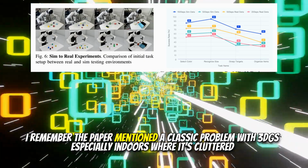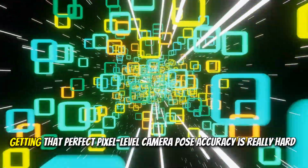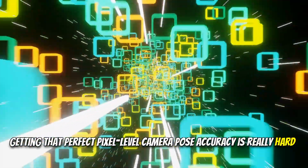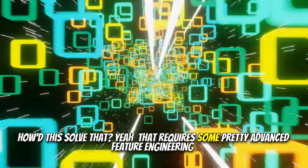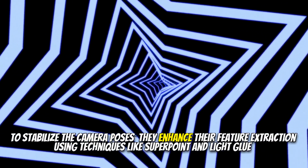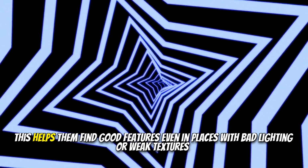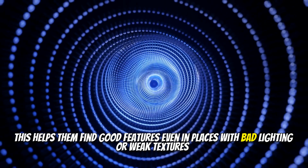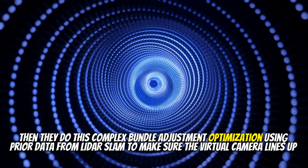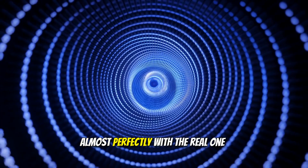I remember the paper mentioned a classic problem with 3D-GS, especially indoors where it's cluttered. Getting that perfect pixel-level camera pose accuracy is really hard. How'd this solve that? Yeah, that requires some pretty advanced feature engineering. To stabilize the camera poses, they enhance their feature extraction using techniques like SuperPoint and LightGlue. This helps them find good features even in places with bad lighting or weak textures. Then they do this complex bundle adjustment optimization using prior data from LiDAR SLAM to make sure the virtual camera lines up almost perfectly with the real one.